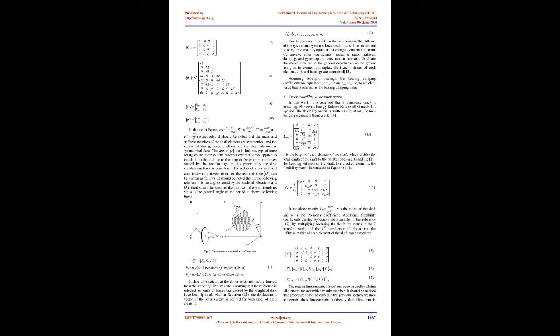Shah and Vakharia, 2019, tested two shafts, one healthy and the other cracked. In the case of the cracked shaft, the experiment was performed with and without the presence of balancing, in order to observe changes in the vibrational pattern, the value and angle of the phase. Differences in vibration responses led to the detection of the crack and crack place.